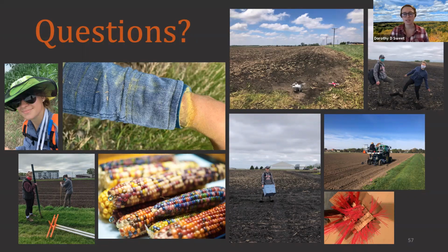On some of the days, there was one day in particular that I took my first flight too early in the morning, and that affected the accuracy of that data. And also there have been a couple of flights where there are clouds that are moving across the field as the flight is taking place. Most of the time that's not a huge issue with this kind of data, but there's one day in particular where there was a lot of difference between the resolution of those parts of the field, and that caused a lot of issues, and that day had to be completely thrown out.